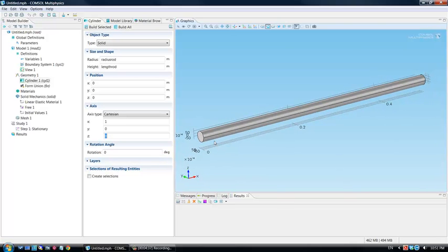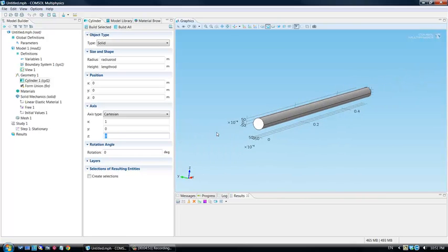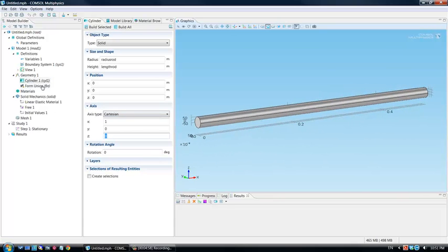Now later on I'm going to compare the deflection of this rod with theory. So just arbitrarily, to show you, I'm going to choose to compare the deflection along the center line. So you see here that this rod doesn't have a center line yet. So I can add one. Adding a line pretty much forces COMSOL to put nodes along the line, and it'll solve the equations for those points. So it'll be a little bit more accurate solution.